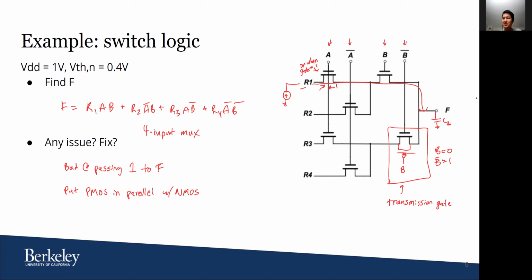But then these transistors in this gate effectively are all passive, right? They don't essentially draw current by themselves, only parasitic capacitances and whatnot. So you're essentially having a path through switches to the output, and the power is being drawn by the gate that drives this whole logic gate. Whereas for CMOS logic, you'll see that the gate itself will draw current because it actually draws current from the supply and dumps it into ground, depending on what the output needs to be. Does that make sense? Okay. Yeah, I got it. Thank you.